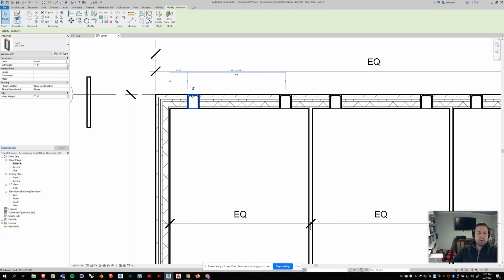So here's my window, and I have this wall way over here. Now, if I just click on these, it's just going to fluctuate through this wall right here: the left side, the middle side, the right side. But I can also click on this point and hold down my left mouse button and move that witness line somewhere else. So now I can click and hit these three parts of this wall.